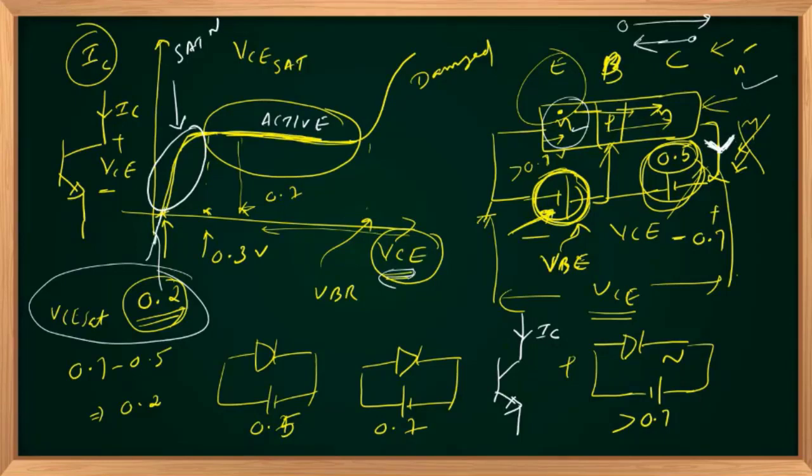So the polarity is different. It goes to even negative. That's why the characteristics is extended beyond zero value to negative. So the current is flowing the other way, corresponding to a turn on of the second junction. Is that clear? So the point we have to remember is that the approximate VCE value corresponding to saturation, turning on both junctions, is nothing but 0.2 volts. Until that, we'll have a maximum current in one particular direction. After that, it changes the direction if VC is negative. Is that clear? Any doubts?